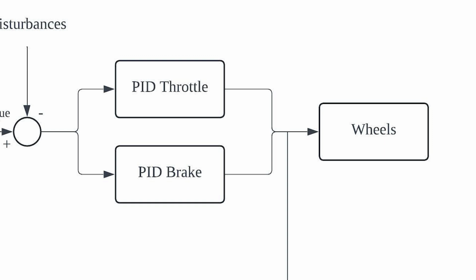For instance, if our vehicle speed exceeds that of the detected vehicles, the PID brakes are activated to decelerate until both vehicles match the speed. Conversely, if our vehicle speed is lower, the PID throttle is activated to accelerate while maintaining a safe designated distance. The actuators transmit the mechanical power to the wheels, causing the vehicle to move at a desired speed.